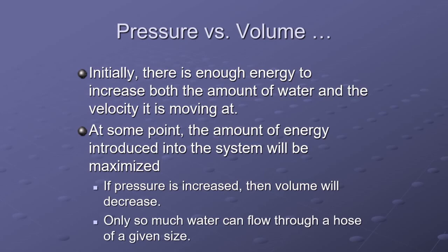Okay, pressure and volume. So we're not really talking about the difference between a pressure pump and a volume pump. What we're looking at is my pump produces both volume, it moves water, and it produces pressure because I've constrained that flow of volume. Generally, we have centrifugal pumps, and we'll get into what exactly that means in a little bit. But when we're using a centrifugal pump, that kind of caps me out in a balance of volume to pressure. And that's where those pump performance charts come into play. At my maximum RPM, I can only give so much volume and so much pressure. And if I have more volume demand in the system, I'm going to be able to produce less pressure.